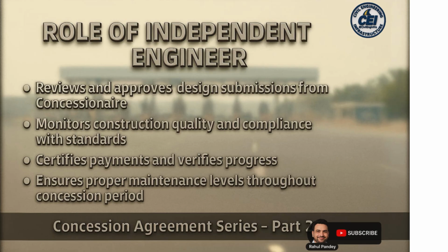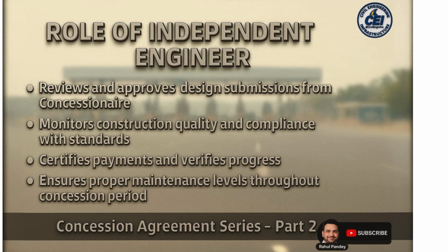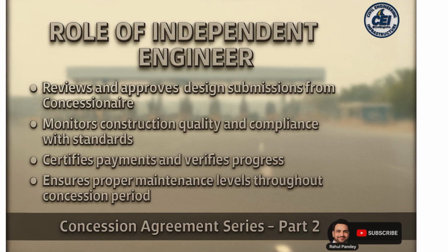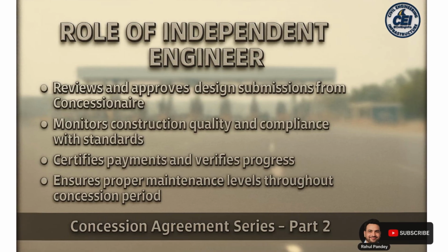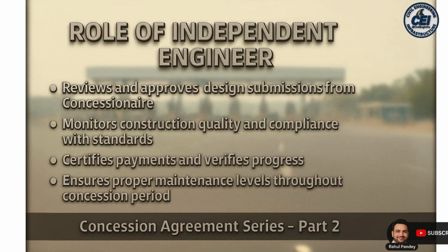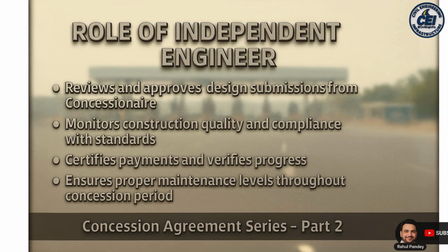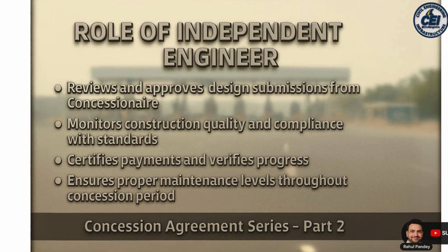Slide 8. Role of Independent Engineer. The independent engineer, IE, acts as an impartial technical arm bridging the authority and the concessionaire. Review or approval of design submissions. Approves designs as per IRC, MoRTH standards. Monitor construction quality or standards compliance. Monitors quality, material testing and workmanship at site.